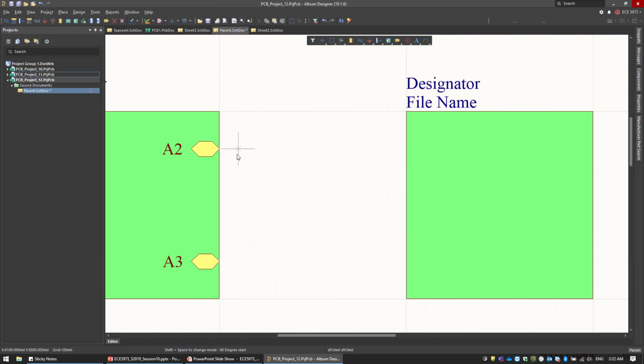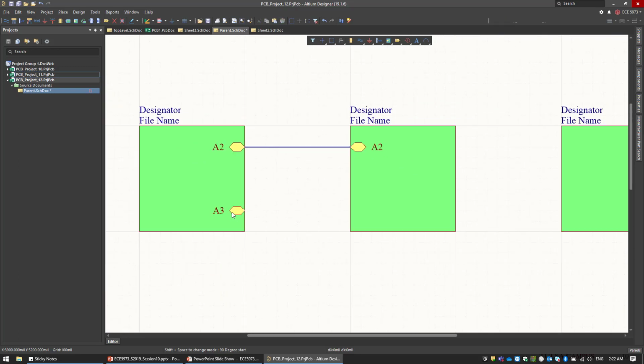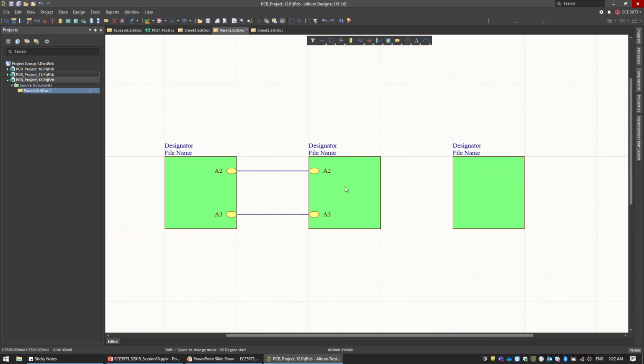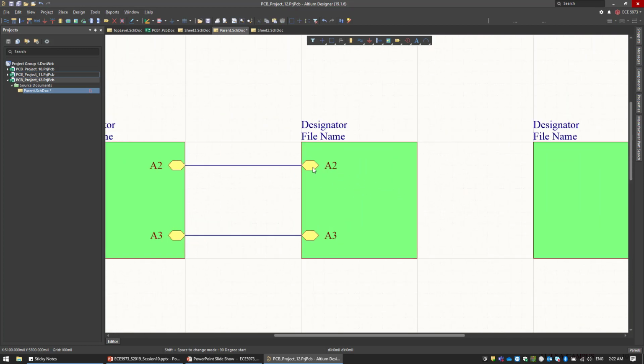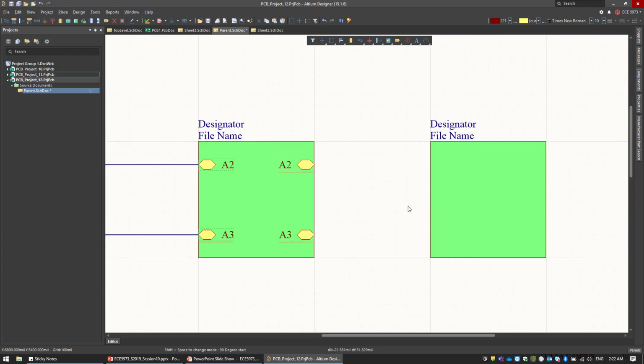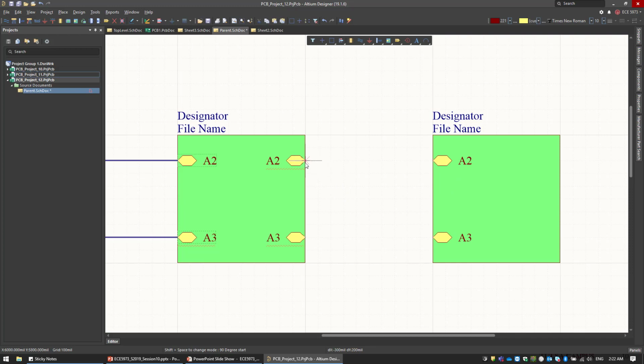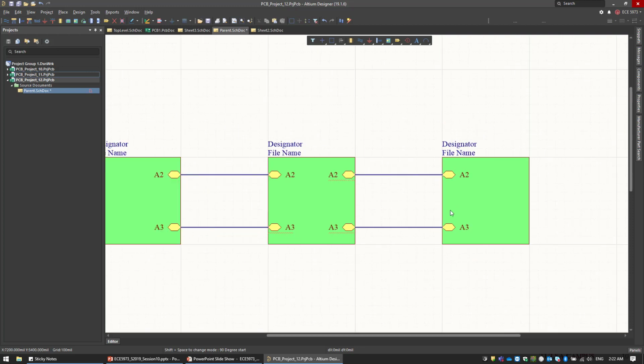Now you have several options. The first option is you can select a wire, and if you try to route, when you come to the side of it, just click on it and the port will be created with the same name. This is very simple. Or basically you can copy and paste the port and this will work as well. So let's try copy and paste. Basically you can copy it in here and copy in here. We are connecting A2 to A3.